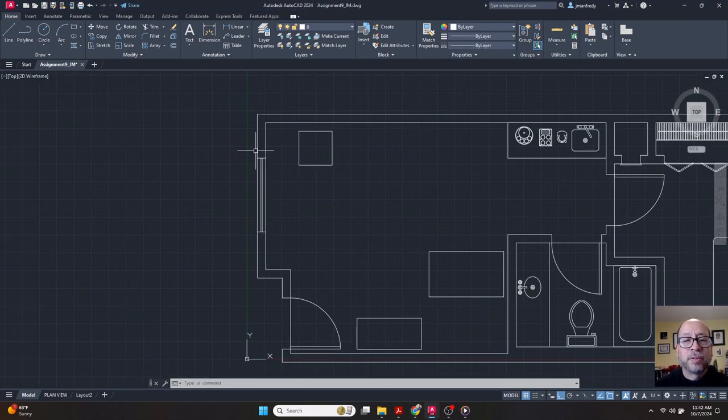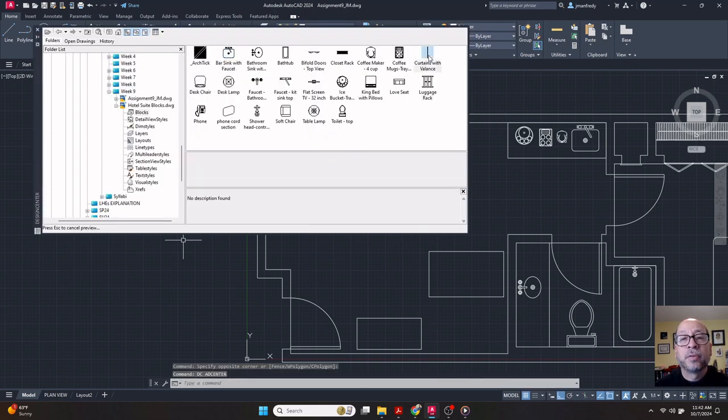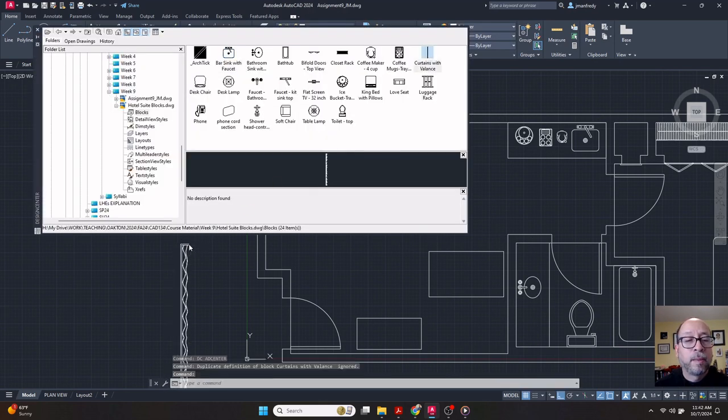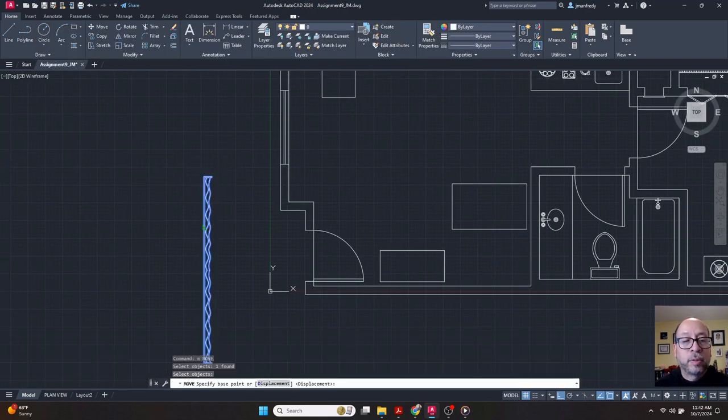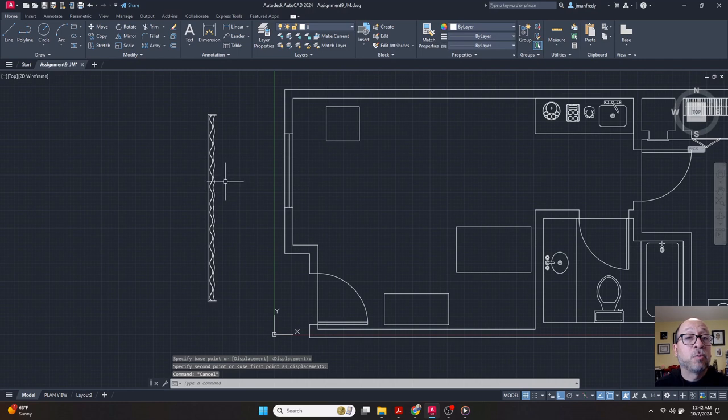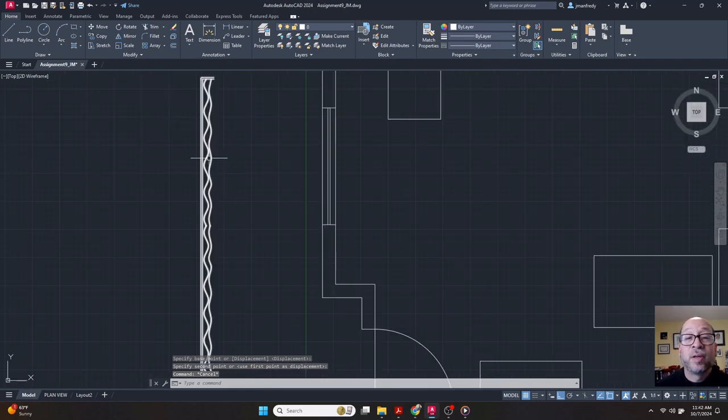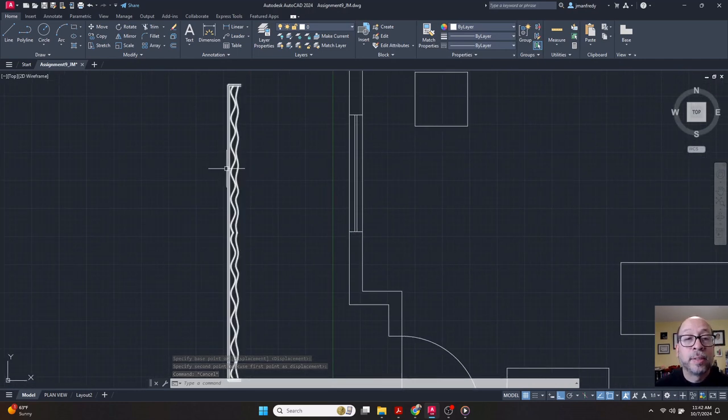This room here has a valance on this window here, and we'll put the valance from the DC or Design Center, DC. I'll grab that valance here, drag it off, drop it off here, and close this. I will move it up slightly, and it's facing the wrong direction. So I need to basically flip it over, which is what the mirror command does.